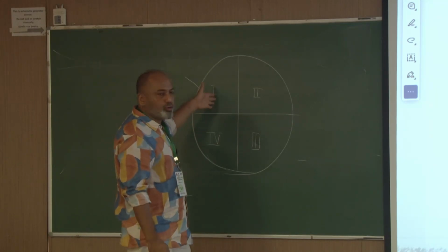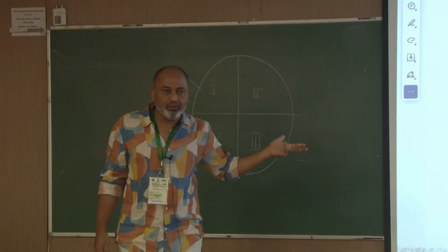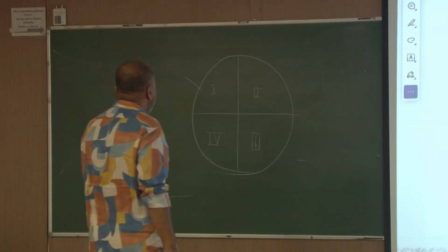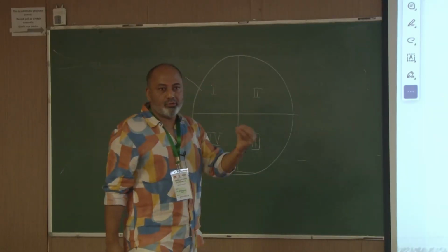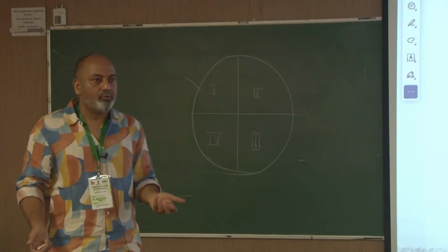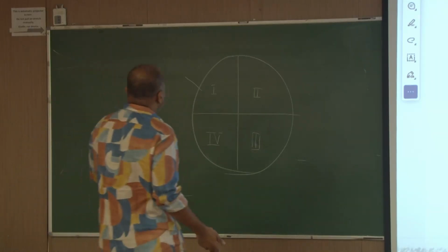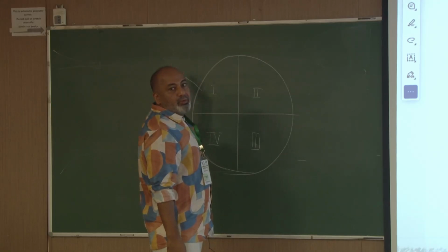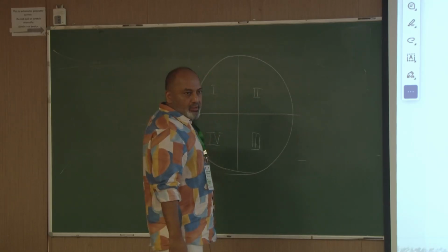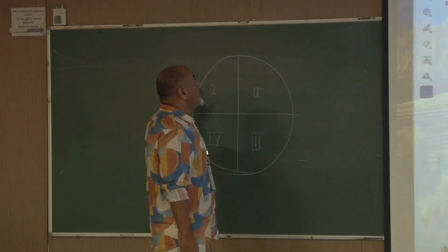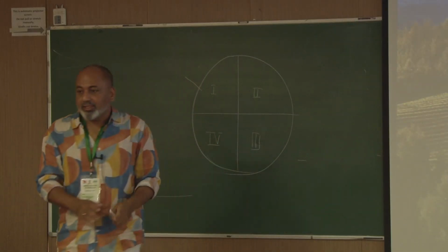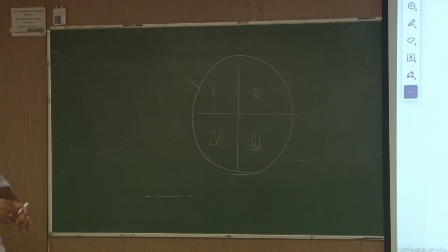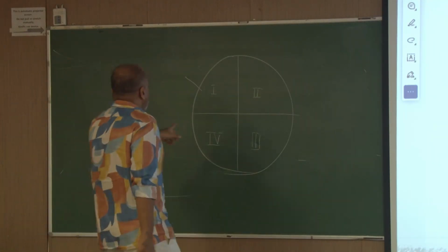These are photodiodes, made of silicon or germanium or some semiconducting material, and when light falls on them they generate electron-hole pairs. That efficiency decides how much current, typically microamperes, is generated for a given microwatt of power. That's the typical efficiency, the quantum efficiency as they call it.